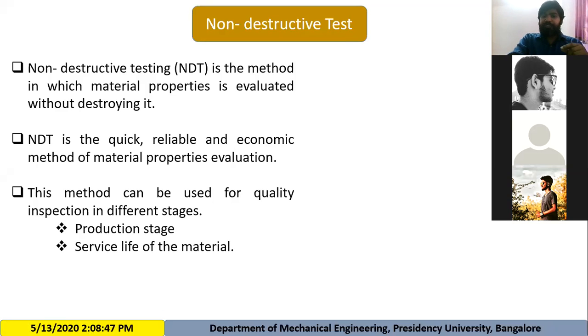The second is the service life of the material. Suppose you have manufactured a component and you have installed it, and you started using that product. So what will happen as time passes? The quality of that product will also deteriorate. So what will you do? Using non-destructive testing methods, you can inspect the remaining service life of the product. Suppose you have made a product and you have been using it for 5 years, then you can perform the testing and predict the remaining life, or predict how the properties are changing with the time period.